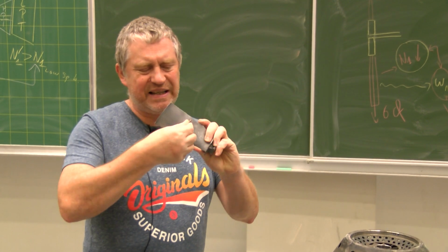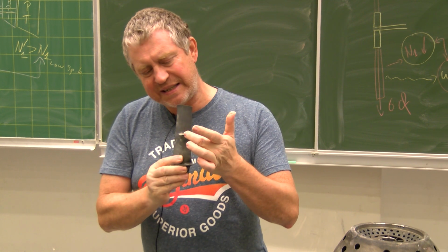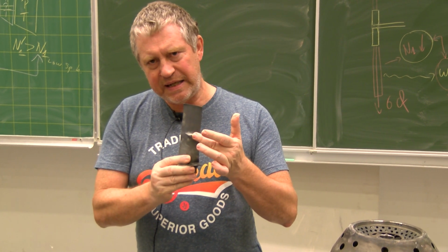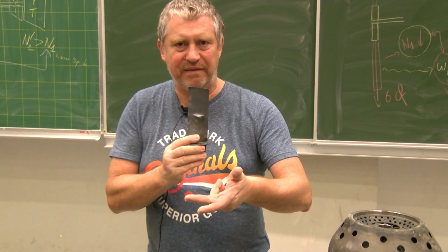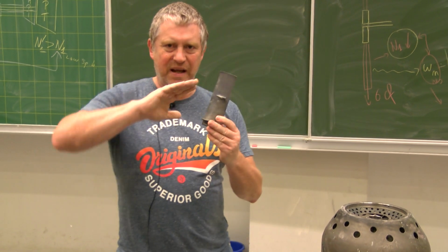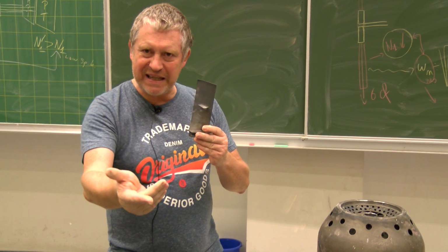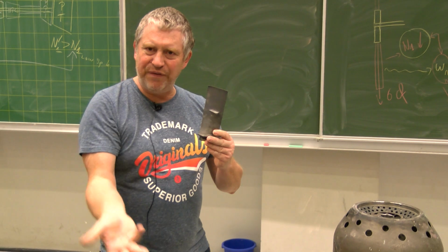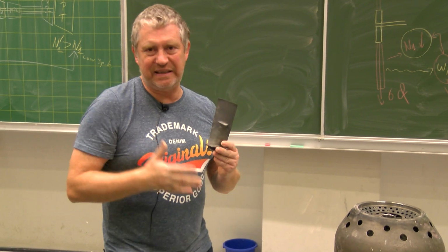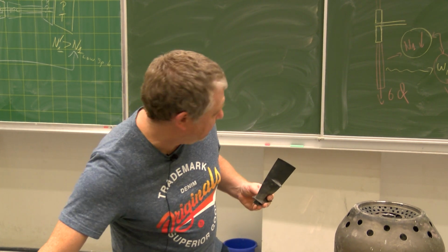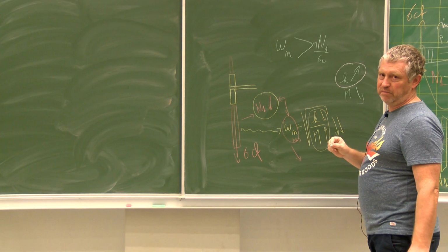You see, at this fin that you have on the blade, this side of the fin is going against this side of the fin of the next blade. And like this, by the contact you have between the different blades, not 30 individual blades, but you will have one single blade that is much increasing the stiffness of the solution.